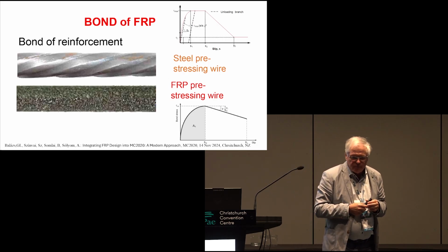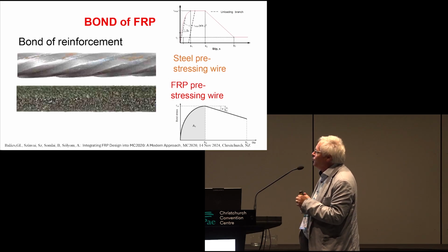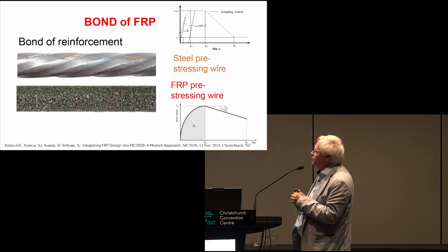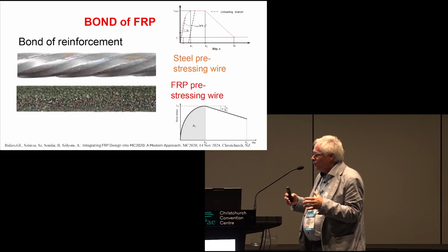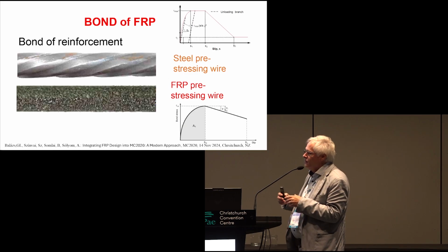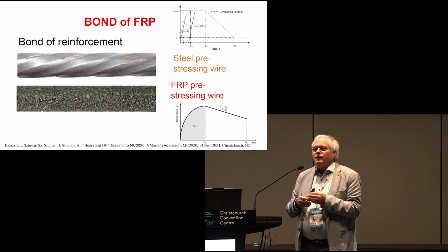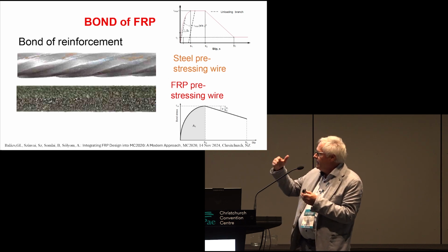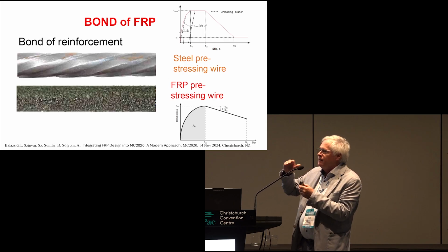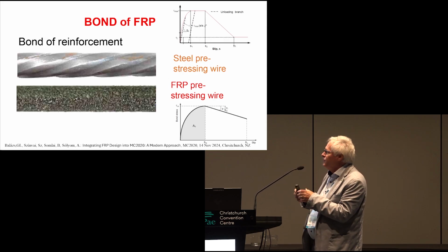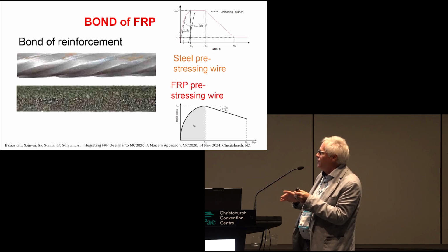During the production, you have to decide how to prepare and finalize your FRP reinforcement. You can see the photo of the differences to steel. The FRP reinforcement has completely different bond and surface properties, which we should consider. Normally, the outer layer of FRP is produced additionally, and the problem is that even under relatively small slip, it can split from the surface.